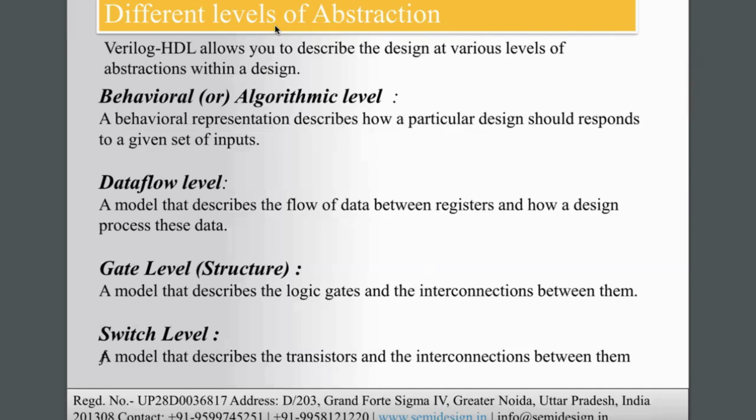What is the next step? We calculate how many muxes are required. If it is to be designed with 4:1 muxes, there will be 4 data lines and 2 select lines.